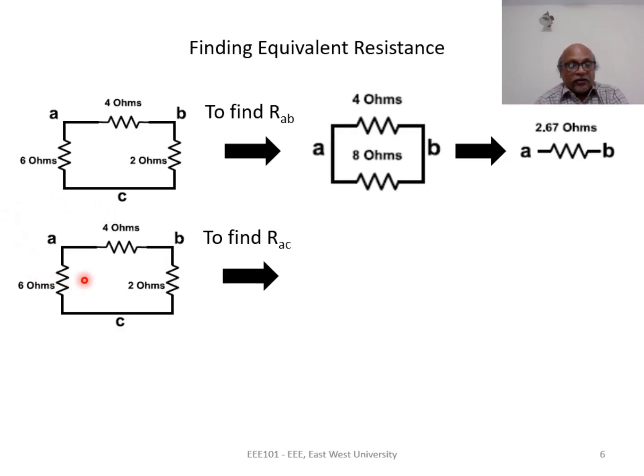That will cause vanishing of node A. And now we cannot combine 6 ohms and 2 ohms either, because that will make node C disappear. So which combination is permitted? If I look at node B, I can combine 4 ohms and 2 ohms. The equivalent 6 ohms will be between node A and C, and node B will vanish. We don't mind if node B vanishes.